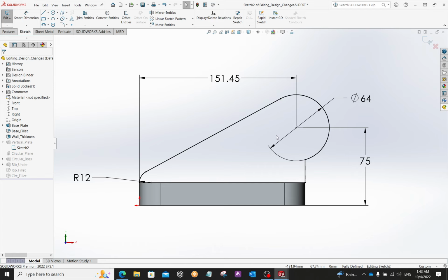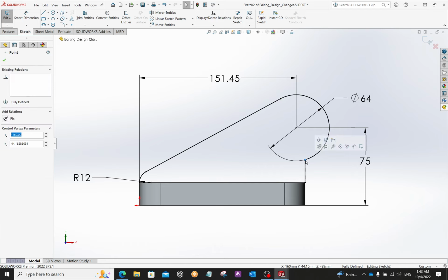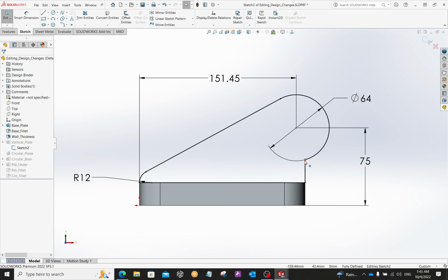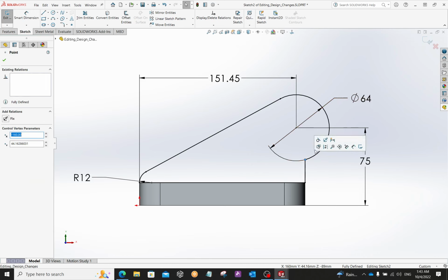So we're editing the sketch, and I'm just going to click this point right here. And then I got the option to make tangent. And little tip here, remember these context menus, if I move the mouse to the left, that menu disappears. So if you're having trouble with it, always move towards the menu. But if you're not going to use this menu, move to the left, it'll disappear.